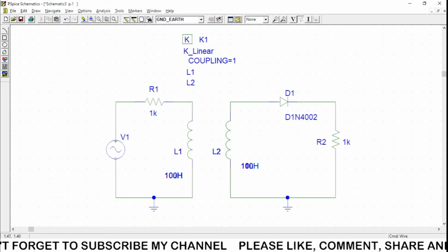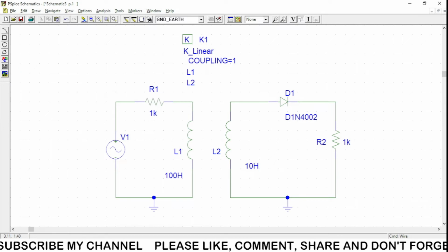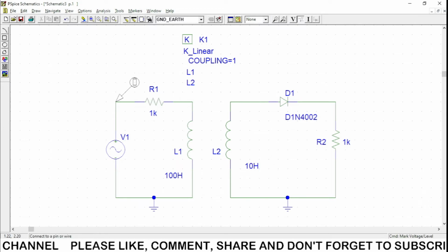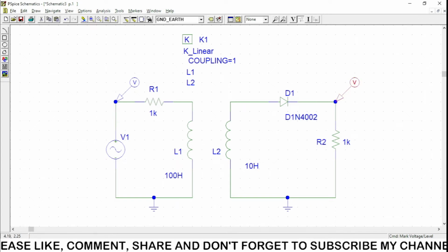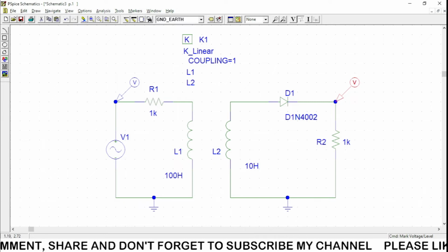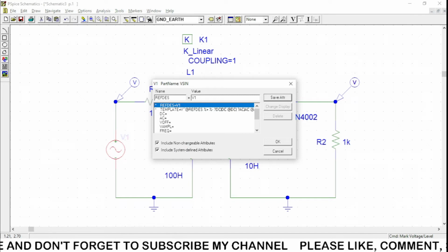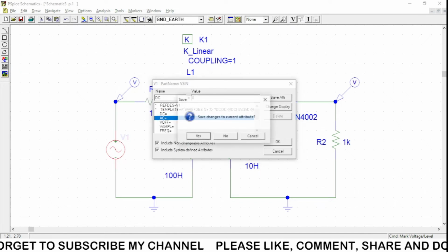Okay, so this is done. So what we need to see is the voltage, meaning the diagram at the input side as well as at the output side, at the load side. So we need to place two markers. Then we need to give V sine parameter. So DC parameter is supposed to be 0.